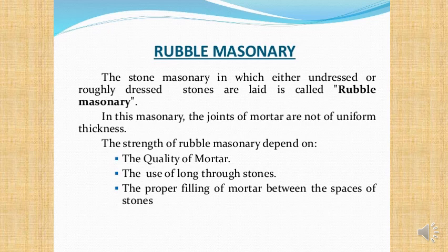Now, remember, the strength of your masonry wall is determined by the mortar in a way, because the mortar is weaker than the masonry block. And so if you have a 20 megapascal strength mortar and a 40 megapascal block, well, the masonry wall you're going to be making will have a 20 megapascal strength effectively, because the weaker of the two materials determines the strength.